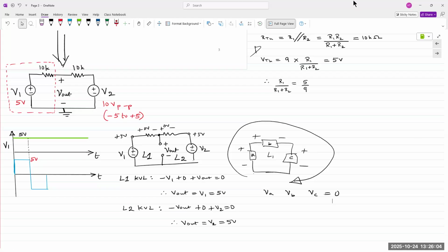You can sum up the voltages clockwise, you can sum up the voltages counterclockwise, it does not matter. You're just adding up the voltages, but you're going around the loop, right? So you can go in this direction or you can go in this direction where you're adding. When I start adding, I always choose the bottom left corner of the loop and start going around.